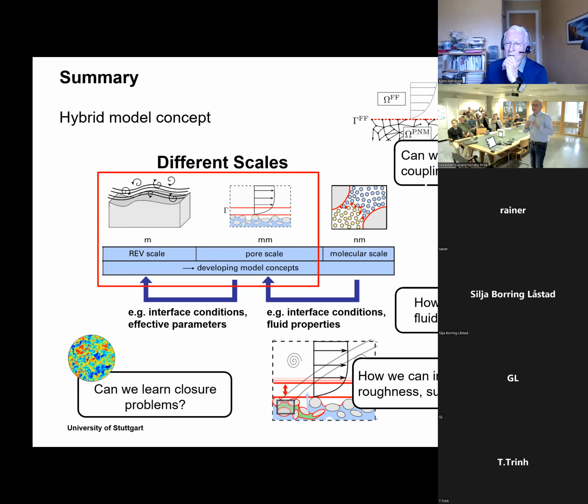No. Beyond that, there are 2 effects. Do you have time to show other slides? No, I will explain it first, and if you like it, I can show you other slides. At first, if you have a wavy structure like this one, then you get eddies related to the wavy structure. And if the distance between the peaks, related to the Reynolds number in the free flow, is relatively small, then you get a controlled eddy between the 2 different peaks. And then, of course, this eddy controls the evaporation process. That means, for instance, that it blocks the system. We have analyzed this.